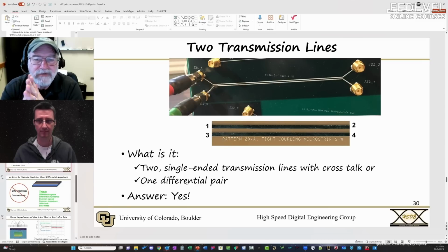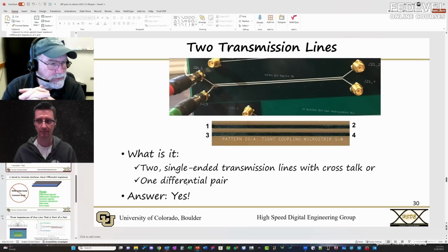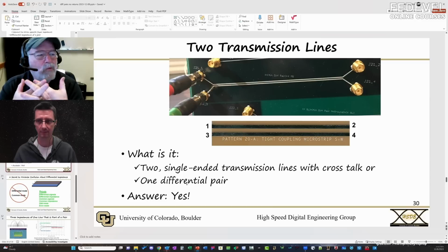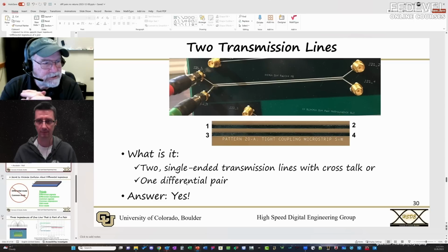And if you have Ethernet, for example, it is multiple differential signals coming off, and I'm going to show an example in a minute here of Ethernet cable, twisted pair cable. And there, the number one most common source of failing, root cause of failing an FCC EMI certification test is common currents on external cables.